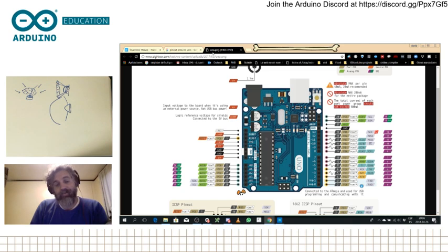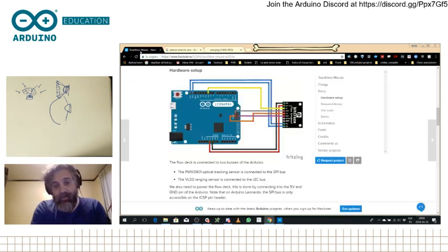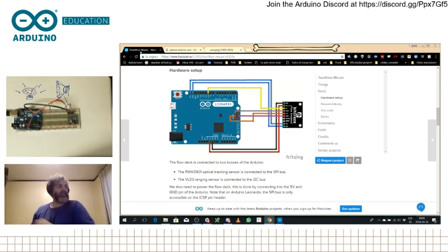So pin number 12 is MISO in Arduino, and according to this, the blue one is MISO. So pin number 12 is MISO, which means that pin number 11 is MOSI. So I just plug them like this. So this is just for the XY detection. I will just try this one out, just to make sure that the connection is working fine.